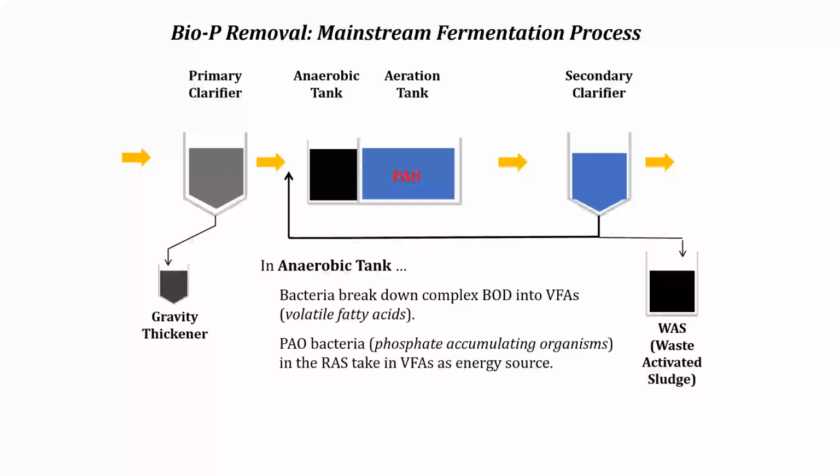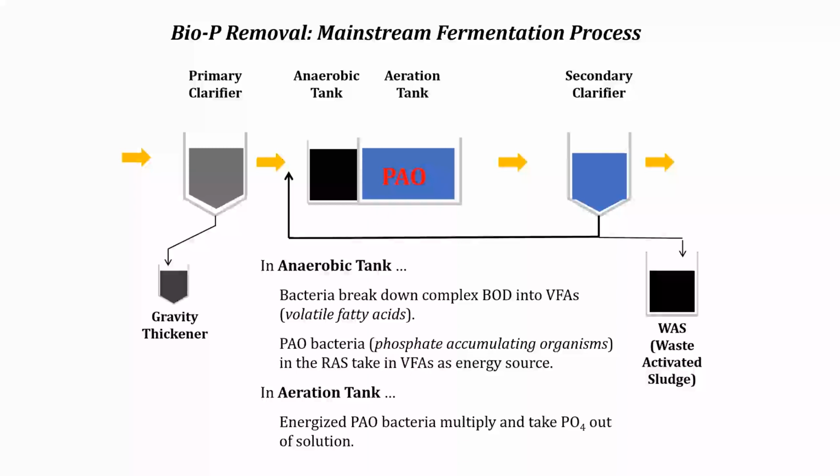As they move in an aeration tank, as long as the aeration tank has that magic 6.8 pH, as long as we're getting good ammonia removal, and as long as there's enough BOD still in the water column to support organic growth, they're going to multiply. We're going to have more PAOs than we did before. As they multiply, they're sucking phosphorus out of solution. It goes into their cells. So now our mixed liquor has a higher percentage of total phosphorus than it did before, because now the soluble is a particulate, right? So it's a total phosphorus.